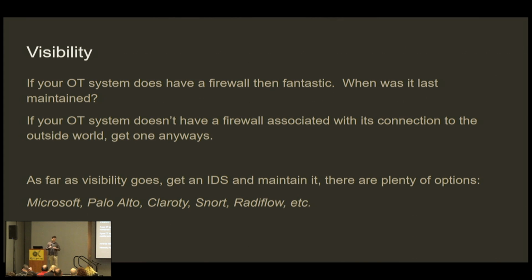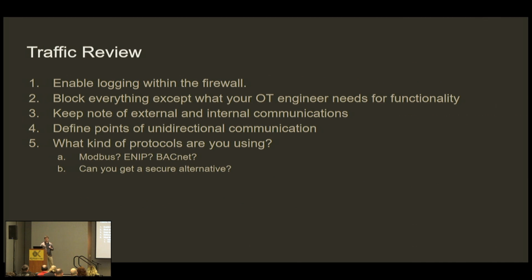And as far as visibility goes over your OT system, you're going to need an IDS, and you're going to need to maintain it regularly. You have a ton of different options in order to do that. Once you have some visibility and you have a firewall, you're going to need to enable logging in that firewall. And then you're going to need to block everything that you can except what the OT engineer needs for functionality.